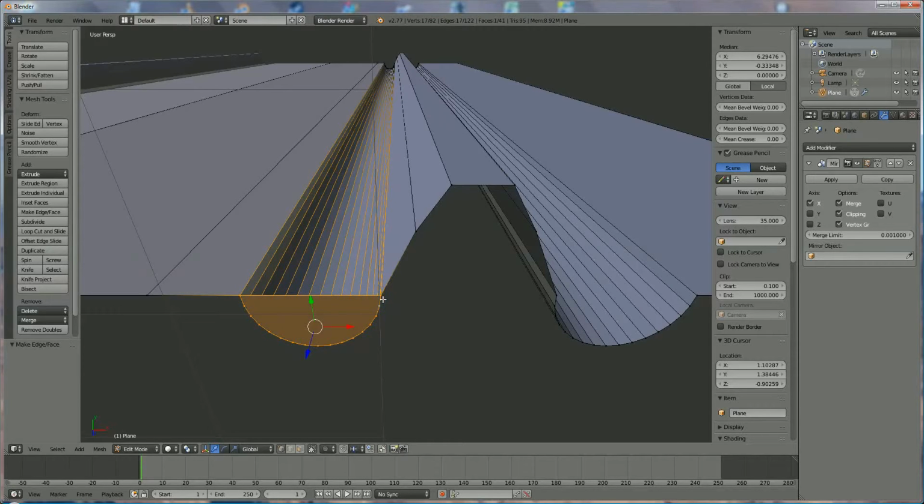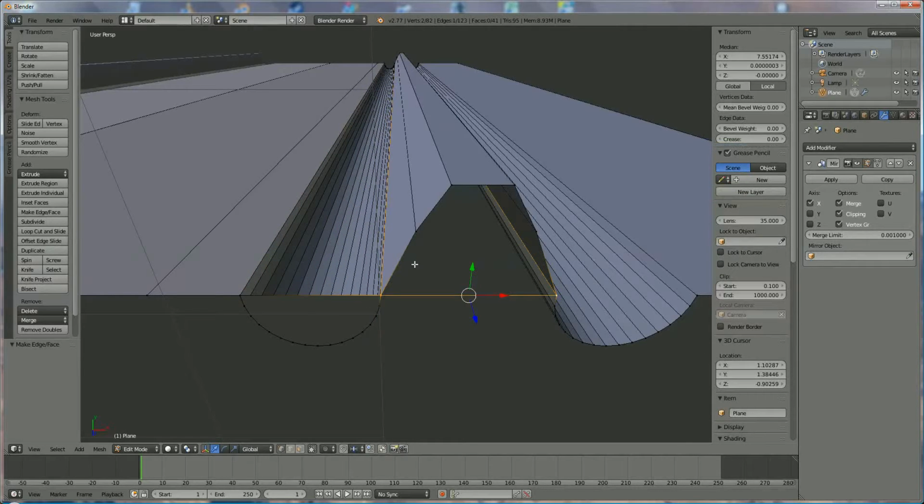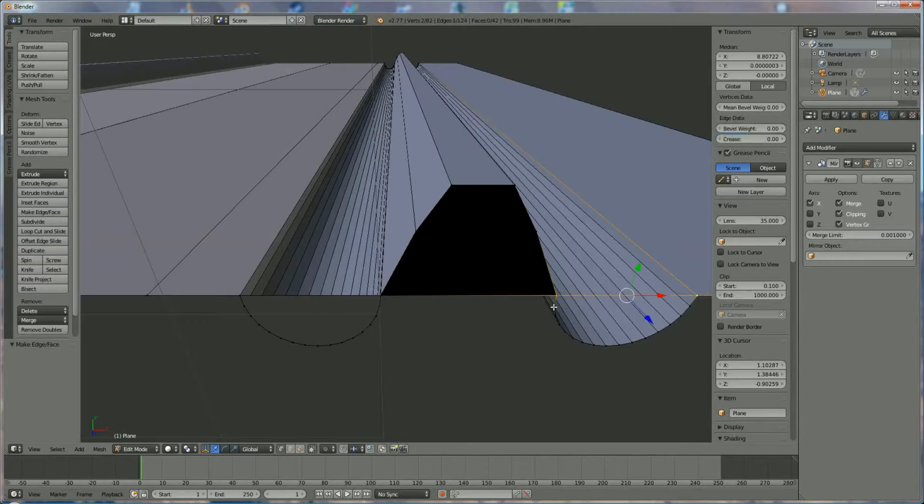Okay, going to do the same over here, right click on these 2 points, press F, hold down the button and click on every other point and press F. Same over here, right click on that point, shift right click on that point, press F, hold down the shift button, and right click on every point you have over here. Press F and it is closed.